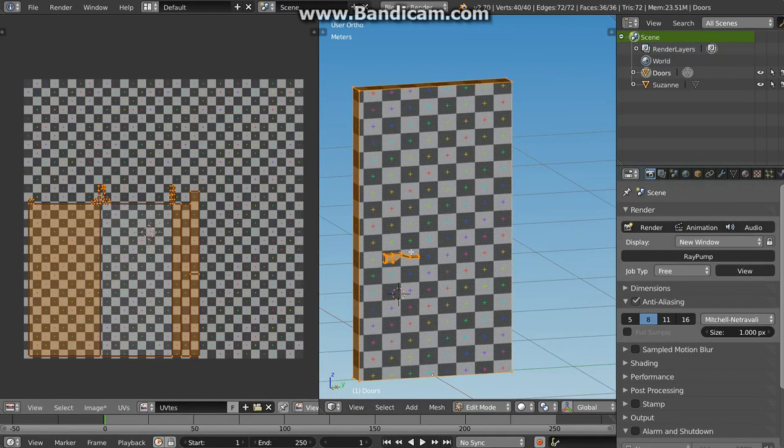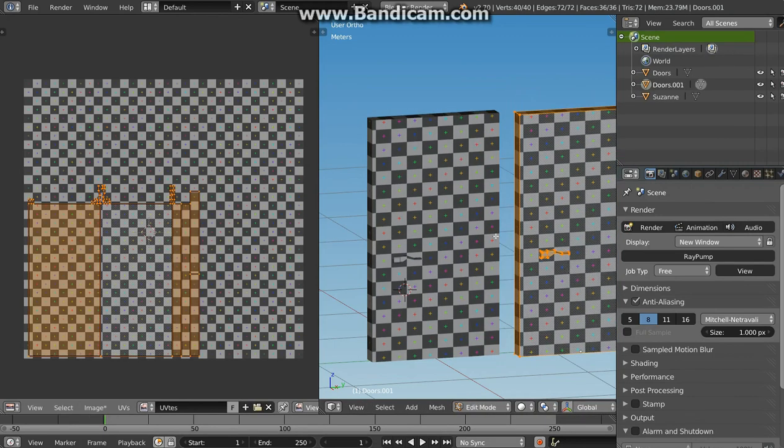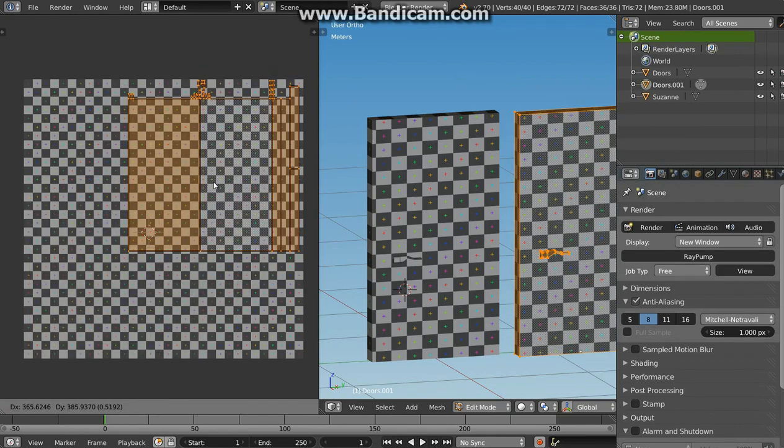But you will probably have more objects in the scene, so learn to use one texture for multiple objects. When you have a different door, just place its UV coordinates on the same texture. So you will actually use the spare space, but never try to fill it at any price.